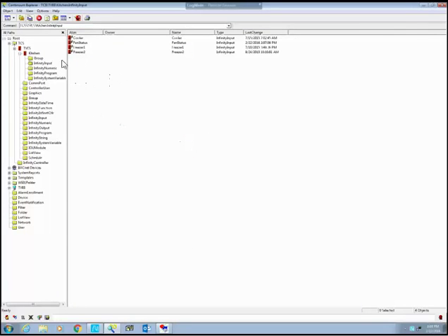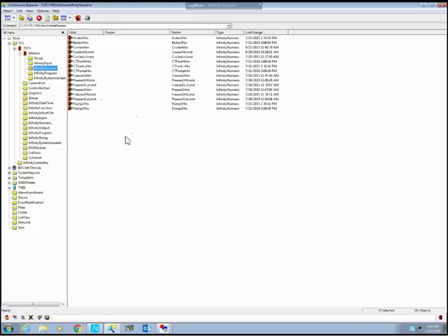Now let's look at outputs. You can see that there are no outputs assigned to this controller. The controller name is Kitchen. There are some histories that we are accumulating. There are inputs that we just assigned. There are numerics. Numerics are just non-physical points. Basically, set points, run hours. Is it occupied? Is it not occupied? So it's non-physical points. It's not inputs.